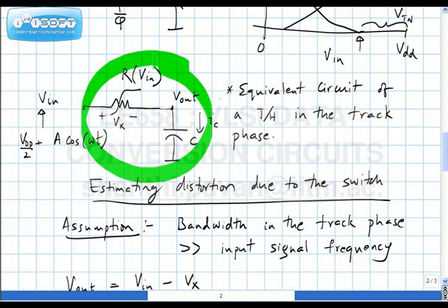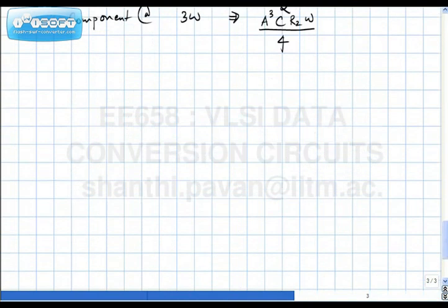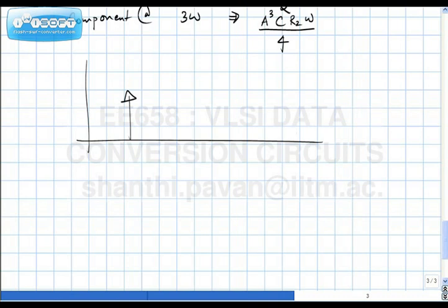Okay. So in the continuous time spectrum, if you put a sine wave here, you are expecting to see distortion products here, only in a monotonically increasing sequence. When you sample that spectrum, you can expect to see the fundamental. Do you follow what I am saying? So in continuous time, if you put in a sine wave, this is the fundamental, and you expect to see some distortion components here, and some multiples like this.